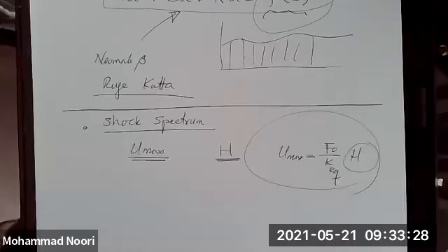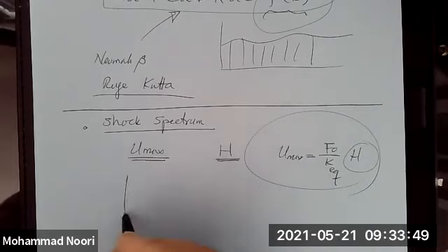But that frequency response function is only valid in the case of harmonic loading, or in the case of periodic loading, because the periodic loads can also be converted to a series sum of harmonic loads. But what happens if you don't have that?